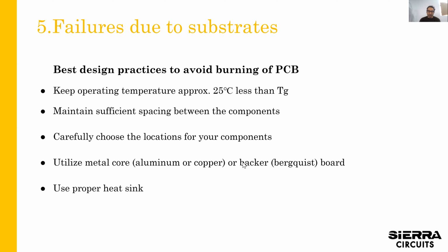And if you do have extreme heat requirements, you can have a metal backed board, or you could have a metal or aluminum core built into the stack up. So you can think about that, think about if you have a very high-end application, how you can use aluminum or copper to suck the heat out of the board.